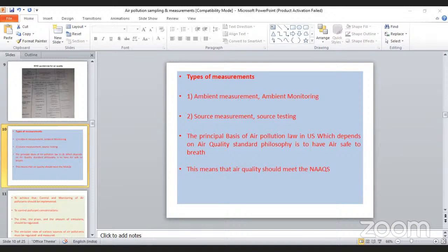When taking an air sample, a known volume of air is bubbled through the glass tube that contains a liquid specified in the method. The liquid is then analyzed to determine the air particles. Whatever enters the first bottle is dissolved in the solvent, and the remaining enters through the outlet to the next bottle. In that collection medium, some of the things are collected, and the remaining exits and enters the third bottle. Some of the pollutant or particles are collected in the third bottle. Something may exit from the third, then it is collected in the fourth.